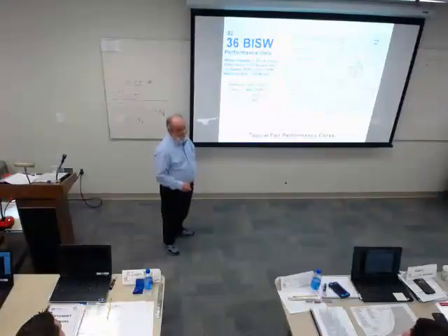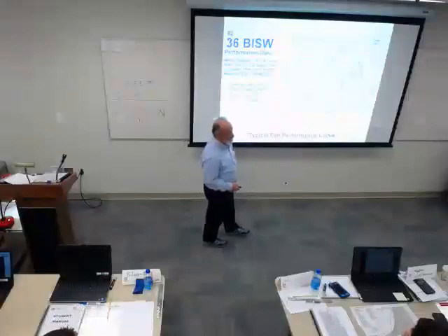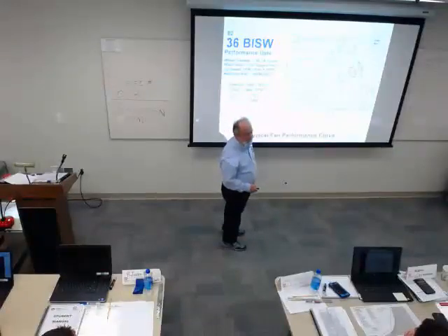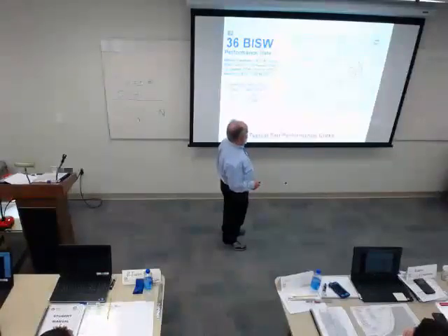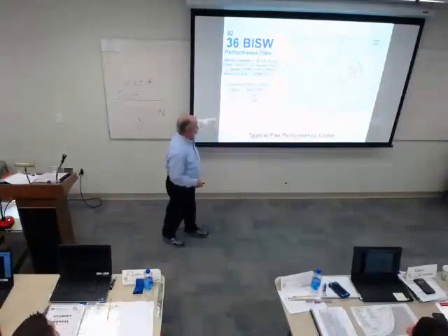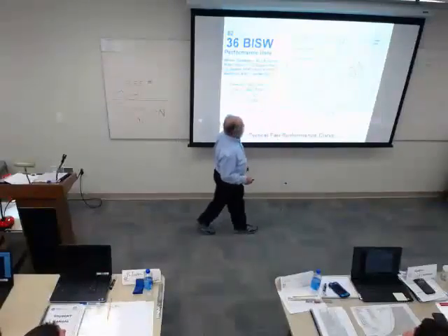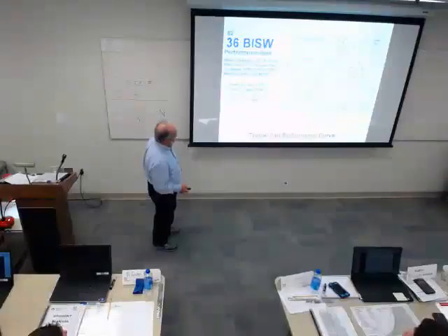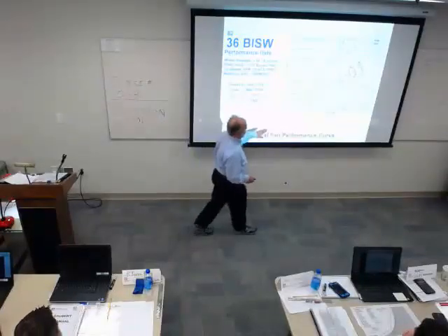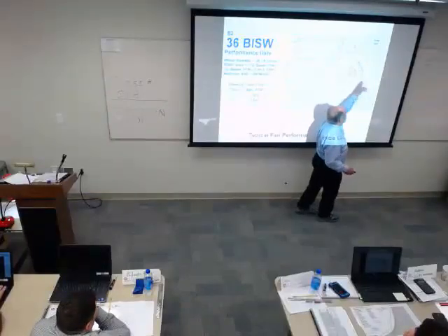You'll see later, these curves are very similar to pump curves, and the problems that fans have are similar to pumps, just because we're working with a different fluid. Pumps actually have the same kind of problem. You back them up here and weird things start going on too. So there's the RPM, and you notice on this curve we have the maximum for the classes. There's the max for class 1, there's the max for class 2.